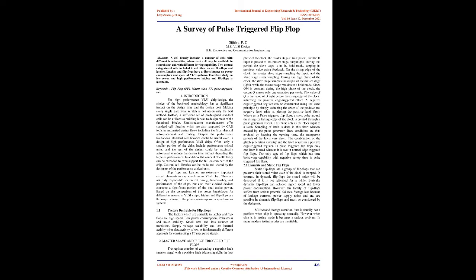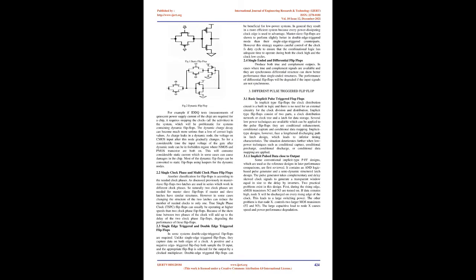Millisecond storage retention time is usually not a problem when the chip is operating normally, however when the chip is in testing mode it becomes a serious problem. In many modern chips, testing modes are inevitable. For example, if IDDQ tests, measurements of quiescent power supply current of the chip, are required for a chip, it requires stopping the clocks, all the activities, in the system, which will be problematic for systems containing dynamic flip-flops. The dynamic charge decay can become much more serious than a loss of correct logic values.